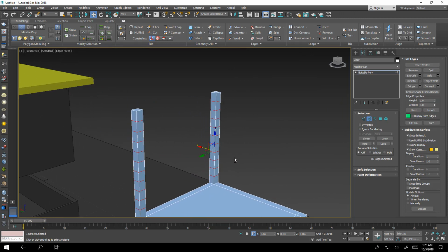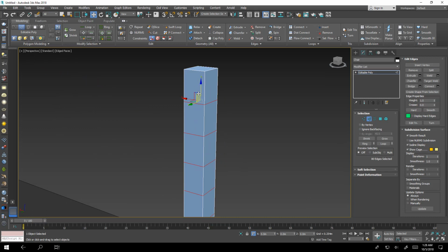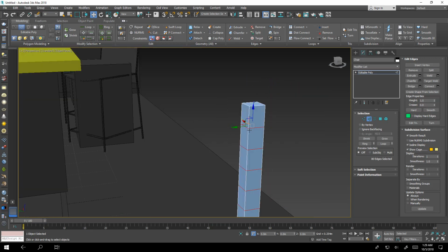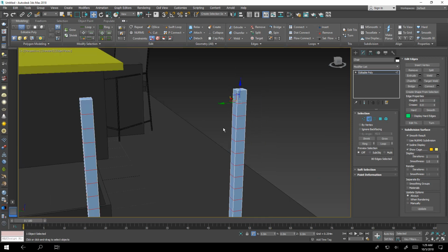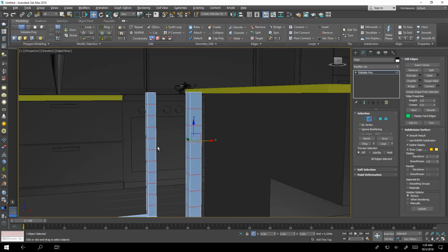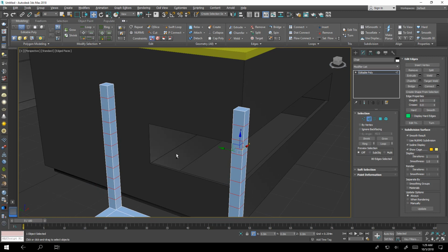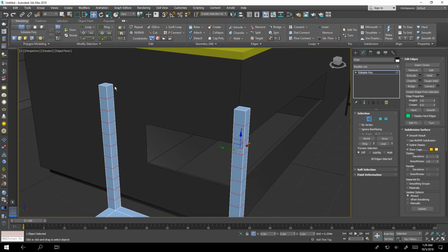Okay. I could have connected between these two edges only, but for continuity issues we will discuss after this, it is better to make loops unless you have very dense meshes, so we will see then what we can do.